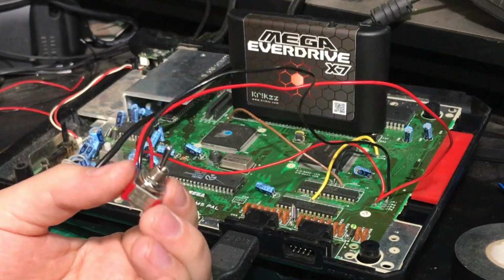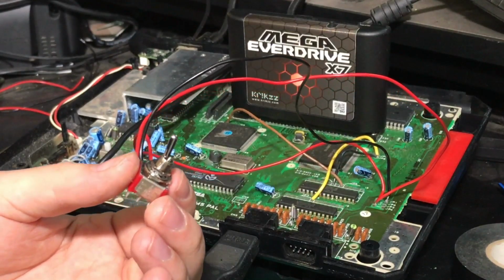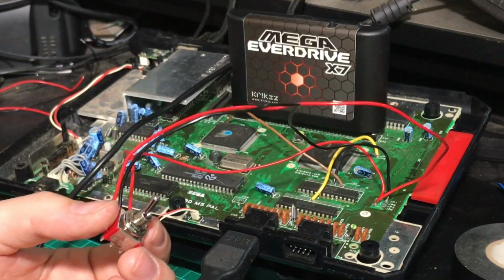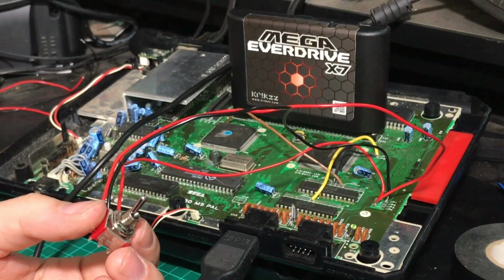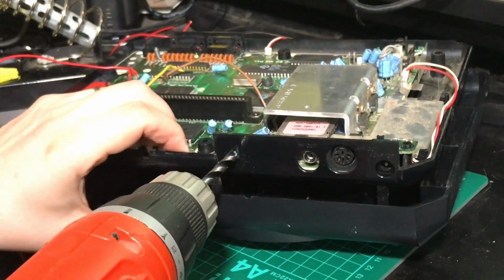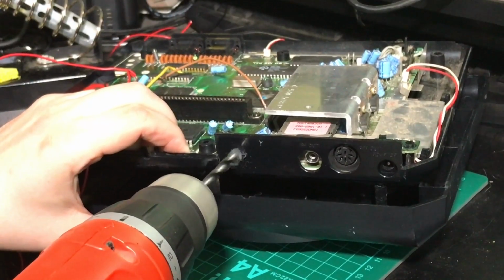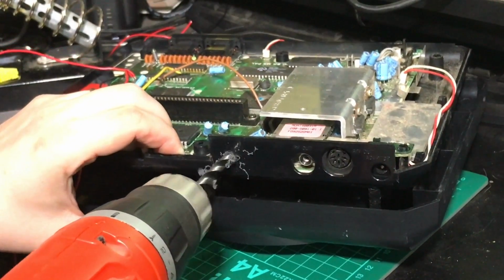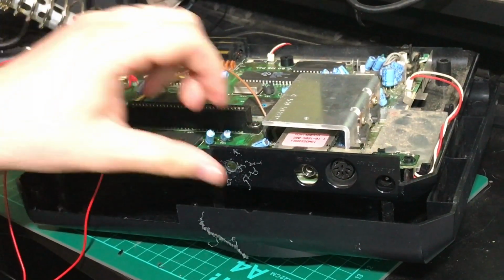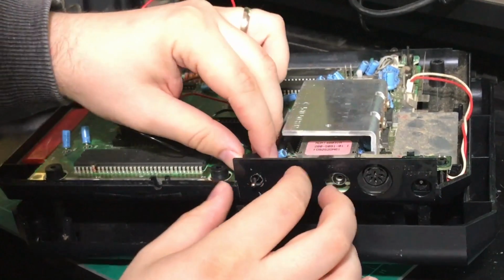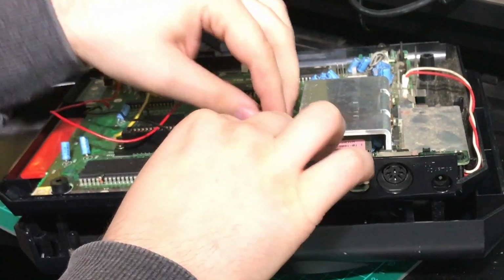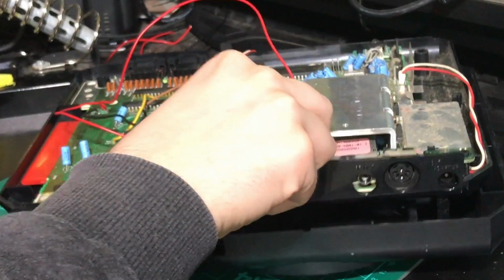You can even change the switch while the console is running and it'll change region on the fly. Before we put everything back together, we need to mount our switch. Because I'm using a toggle switch, this is a pretty easy job. I'm going to mount it on the rear of the system, and to do that you'll need to drill a hole. Try and line up your switch to make sure the whole thing will fit where you want to drill the hole. For this particular switch, I drilled a hole using a 6mm dowel drill bit. Be careful that you don't plough it through your Mega Drive's components. Once that bit was done, I could insert the switch and screw it in. If you used a different type of switch, you might need to use a file to make a suitable hole, but it's not too difficult.